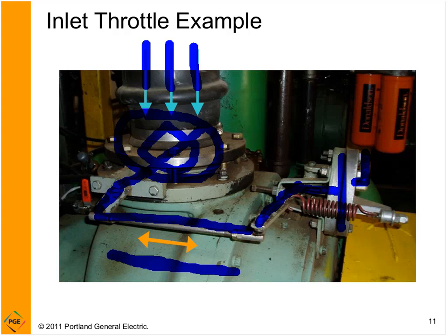Then once the pressure in the plant reduces because we're taking out air, let's say we increase the demand, turned on another production line, then the pressure will drop, and then the spring over here will pull the throttle open. So it normally wants to be open. If I left it alone, it would be open, but once we apply pressure to the diaphragm, it will begin to close. Okay. And this is very, very simple. Nothing complicated. It's kind of like the linkage on your old carburetor.